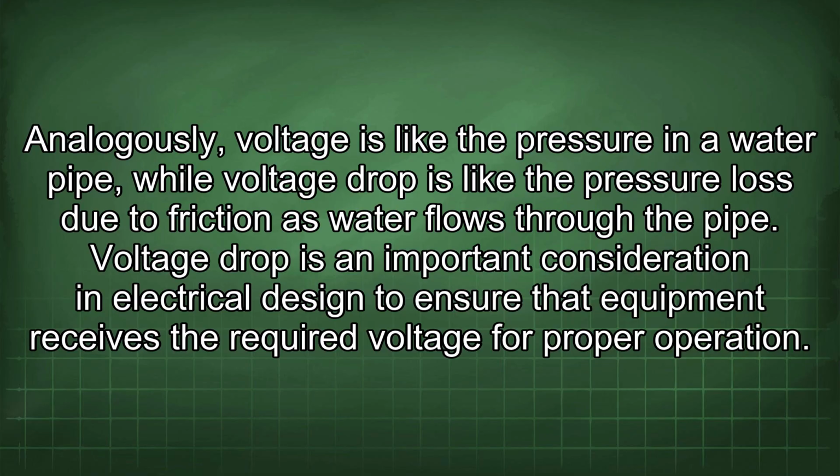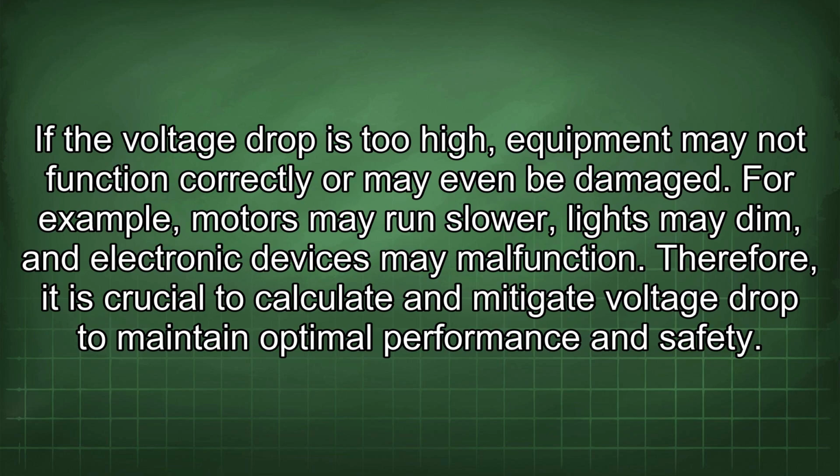Voltage drop is an important consideration in electrical design to ensure that equipment receives the required voltage for proper operation. If the voltage drop is too high, equipment may not function correctly or may even be damaged. For example, motors may run slower, lights may dim, and electronic devices may malfunction. Therefore, it is crucial to calculate and mitigate voltage drop to maintain optimal performance and safety.